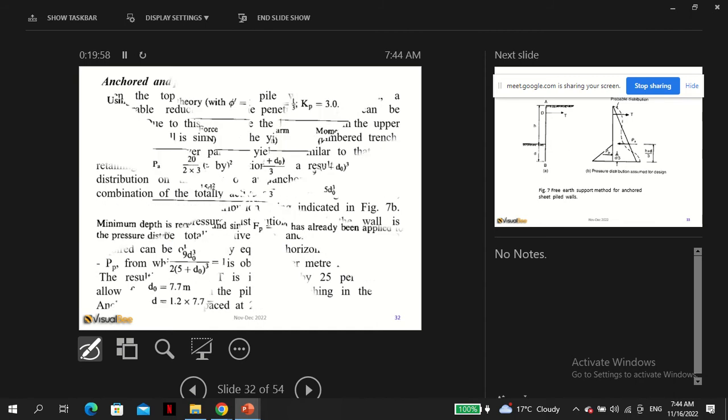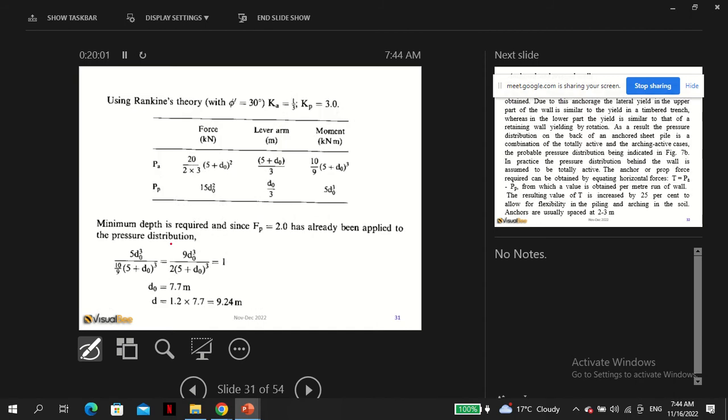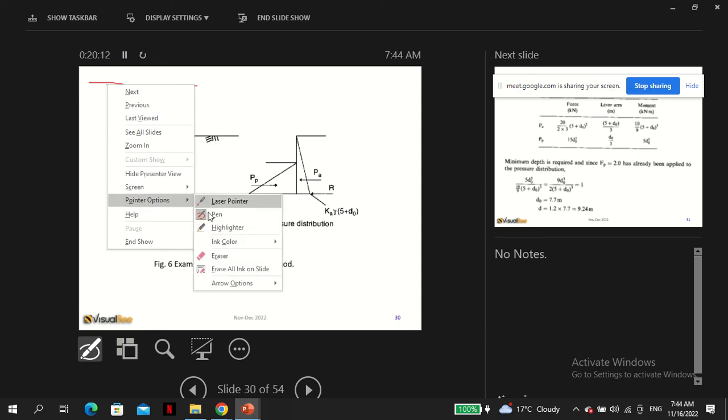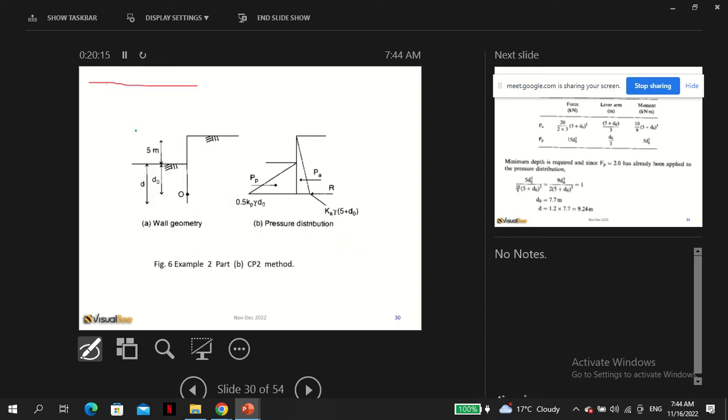Arching is this idea observed in sand. I think I've said it in this class. In theory we know that the pressure distribution here is, so this is the vertical force we are talking about, gamma times Z. And so in theory, if you have an infinite depth, then this curve will continue in a straight line.